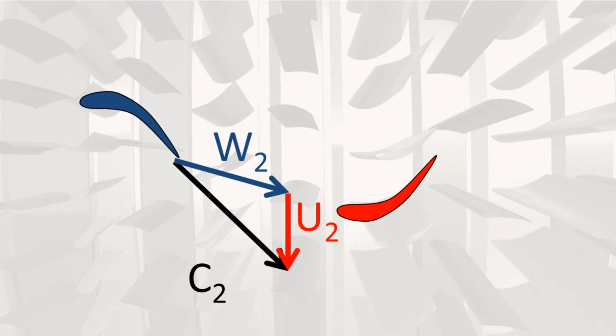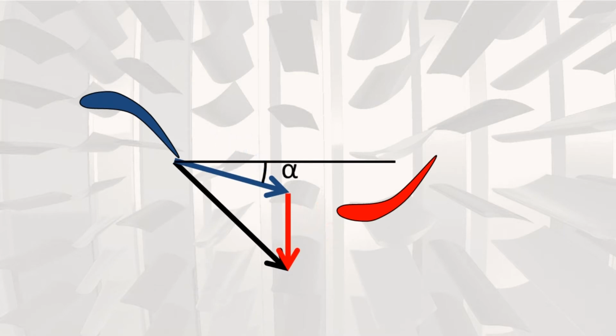Just like the wings of an aircraft, the blades are aerodynamically shaped profiles. One issue when sizing either aircraft wings or rotor blades is the development of boundary layers, which eventually can lead to stall. In this case, the efficiency is decreased and in the worst case can eventually result in engine failure. This results in limiting the values for the angles alpha and beta. The way one sets alpha and beta also affects the pressure drop in energy extraction.